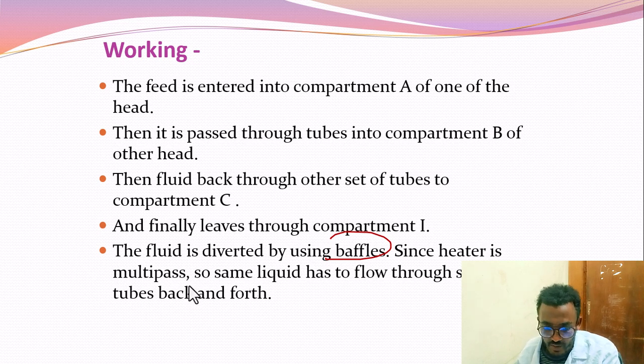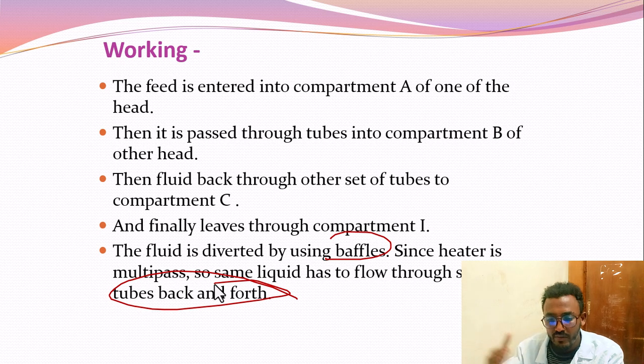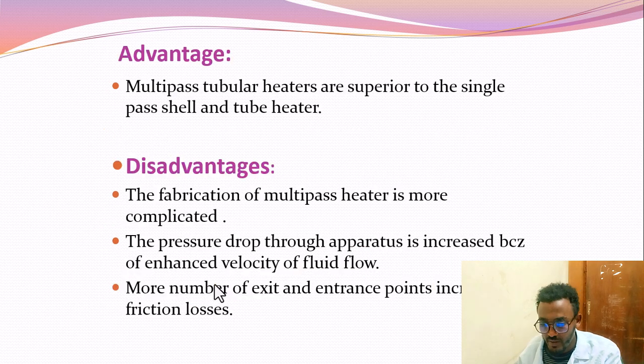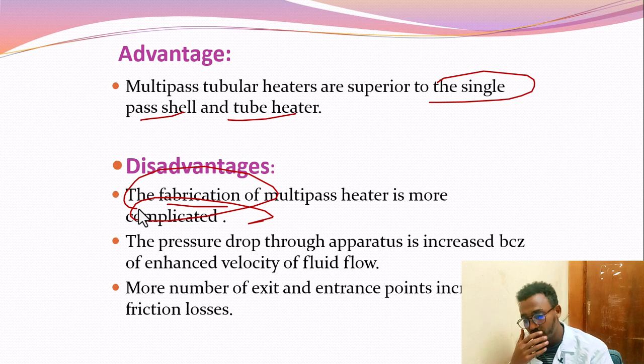Since the heater is multi-pass, the same liquid flows through the several tubes back and forth. As I said before, it's a kind of rocking chair mechanism. They move back and forth before they leave the equipment. The advantage is that they are superior to a single pass shell and tube heater. The disadvantage is, first, that fabrication of the heater is more complicated, so there is a kind of complicated fabrication if we want to develop these heaters.